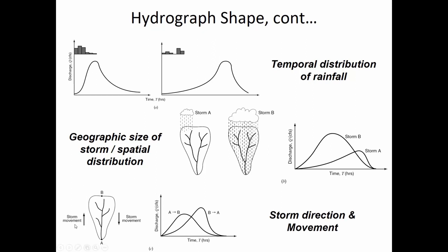All right, now this effect is maybe trickiest of all. And this is something that you often can't see in the rainfall data. When we talk about variability, sometimes just the hydrograph that you're looking at, the historical flow data from a watershed, looks different than you were expecting. So what this is saying is consider two different cases. In one case, the storm was falling on the watershed, and these are both the same amount. In the first case where the storm movement was from A to B, and when the storm movement was from B to A, the amounts were the same.